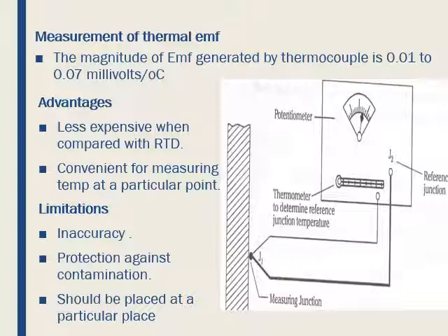Some of the limitations, as I already mentioned: they have low sensitivity and are inaccurate. Protection against contamination should be given, because they are dipped into the metals in some applications. They should be placed at a particular place so that they require point sensing. Higher cost than other temperature transducers. These are some of the limitations.